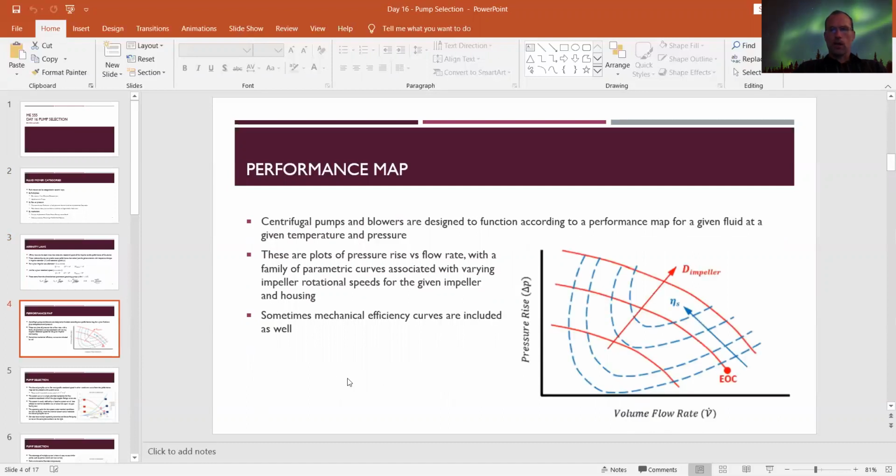It's what we get from pump curves. The manufacturer is going to give you a pump curve, which tells you what the pump performance data is. It's generally given as a flow rate on the x-axis and a pressure drop or head loss on the y-axis. Again, those things are kind of interchangeable. It shows you, for some given diameter and some given rotational speed, how that pump is going to react, and based on different flow rates, what sort of head the pump produces.